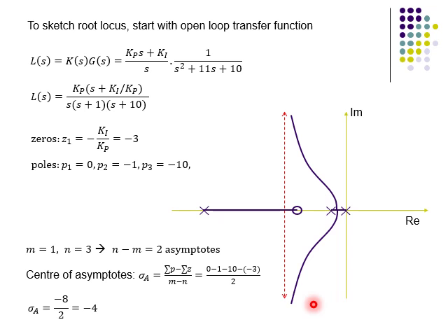So this pretty much completes the diagram or the sketch of the root locus. Of course, we should add some arrows to show the directions that the poles move in for increasing Kp. So just to summarize, to get the root locus diagram, we fix the value of the controller zero. So we fix the ratio of Ki over Kp to 3, so that the controller zero is fixed at this location here, and that allows us to construct the root locus for changing the value of Kp.